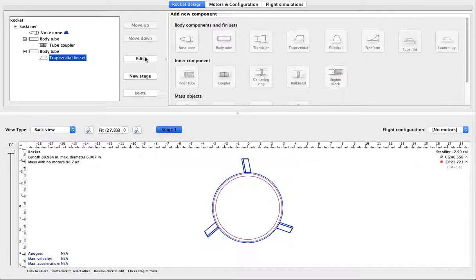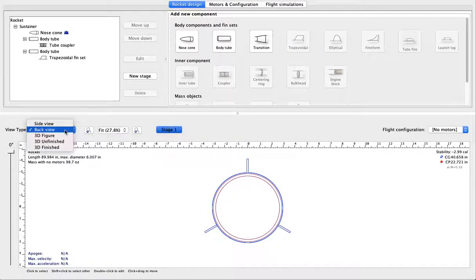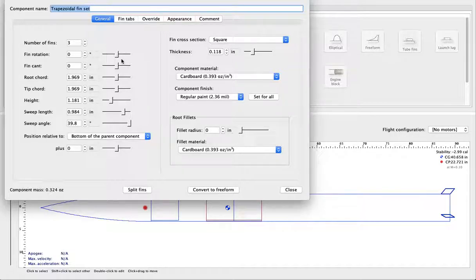Now, why would you do this? Well, you would do this because some people like a flight where it intentionally twists so that it makes it more stable, kind of like a Nerf football when you're throwing it through the air. We don't do that. Maybe we're in the wrong, but I know what's worked, and I've never seen that on a high altitude rocket, probably because of the stress it puts on the fins, especially during supersonic flight.